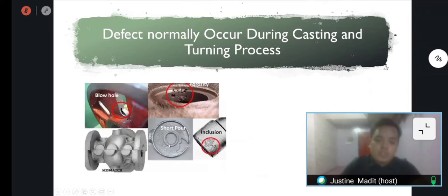It may happen because the mold is not filled, so it does not form a complete shape, as you can see here. The remaining part will not be finished, or the gating system is blocked somehow, and as you can see, it is caused by a blowhole. It can lead to the product collapsing, or being totally broken or damaged.